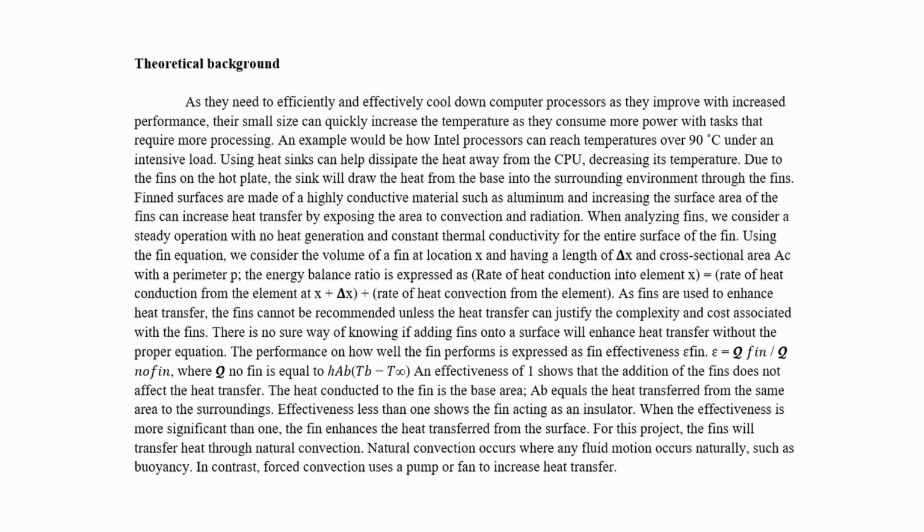The heat conducted to the fins into the base area, A_b, equals the heat transferred from the same area to the surroundings. An effectiveness less than 1 shows the fins acting as an insulator. When the effectiveness is greater than 1, the fins enhance the heat transferred from the surface.